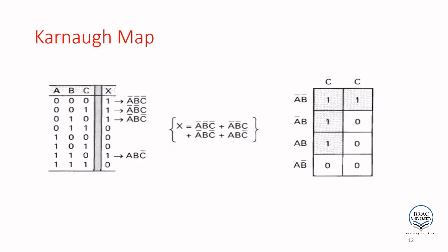So this is basically a 3 input K-map. You have 3 inputs, so 8 combinations. You are given 0, 1, 2 is high and 6 is high. So just put some together, this 3 and this one. This is your X. So how can you draw it in the K-map? So this is a 3 input K-map. You have 4 columns, 2 rows, or you may have it the other way, 4 rows, 2 columns, both are fine. So you can represent this like this: A prime B prime, A prime B, A B, A B prime, or 0 0, 0 1, 1 1, 1 0.